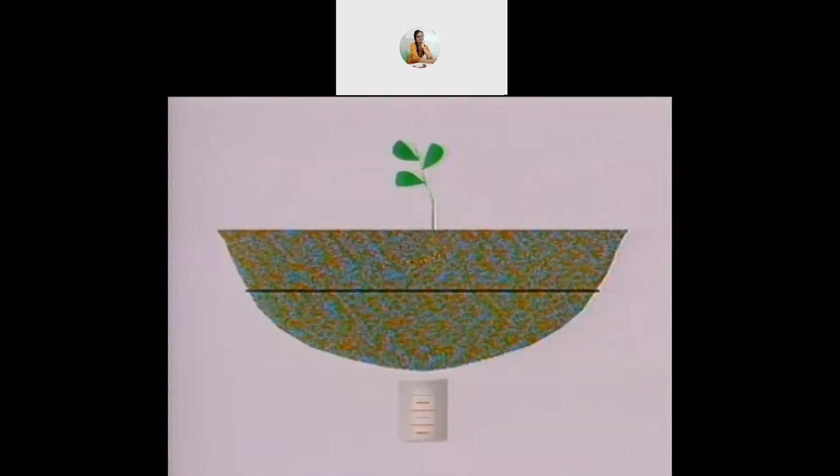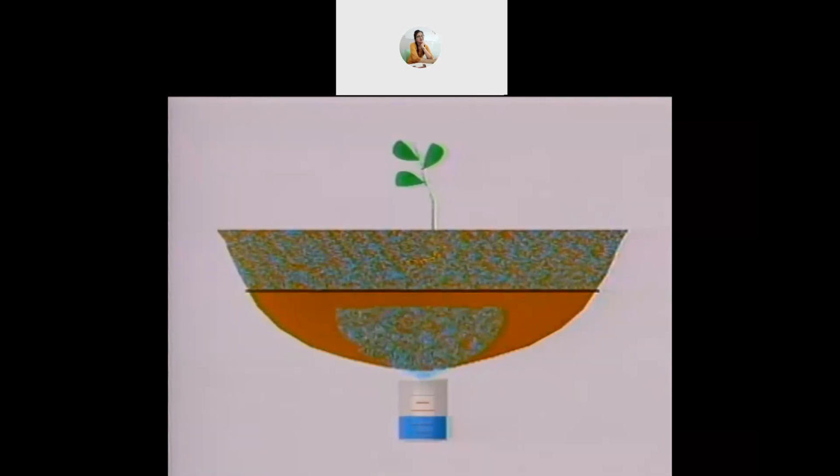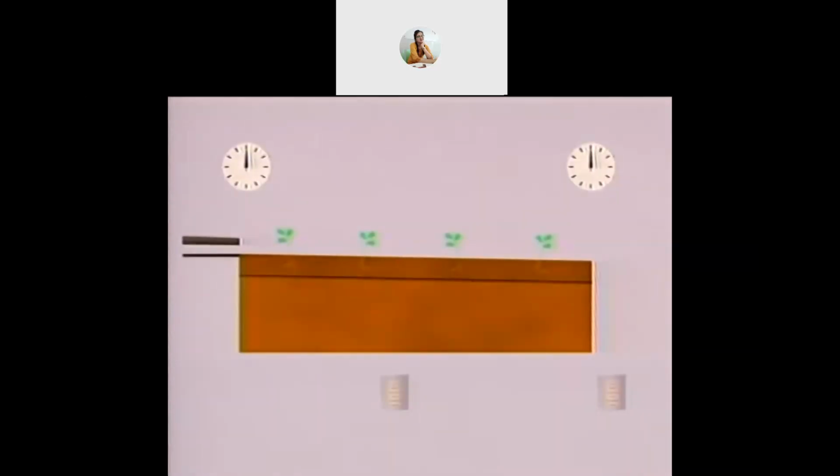Your goal is to apply just enough water to fill the root zone without deep percolation. So far, we've looked at what happens in a small area of the field. Let's look at an irrigation of an entire row. You start water running at the head end of the field. We'll start our opportunity time clock at the head end.